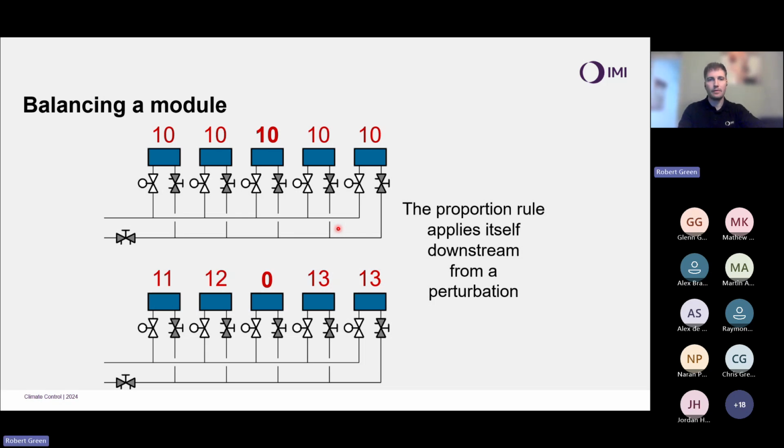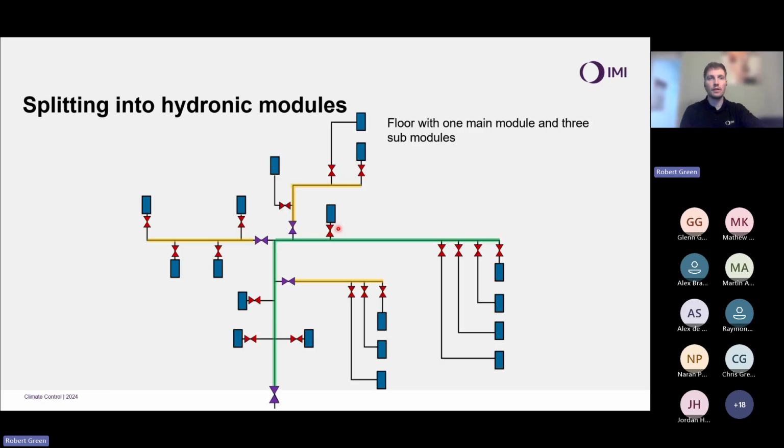Another important topic we covered in the first week was looking at how we split systems into modules. And once again, we want to imagine ourselves when we're splitting it into a module. In particular with DPCVs, differential pressure control, it's really imperative we follow this same module structure because we need to ensure all areas of my system are created using some form of differential pressure control. And I often use the word protected by a form of differential pressure controller.